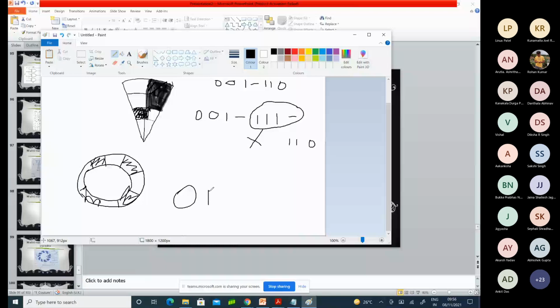And what will be the output of it? The output will be a kind of sinusoidal wave, with theta on one axis and voltage on the other, because it will not be a perfect square wave. Now you apply a Schmitt trigger on it. The Schmitt trigger will give you a perfect Vsat or minus Vsat. So for theta versus voltage V, you will get a perfect square wave.